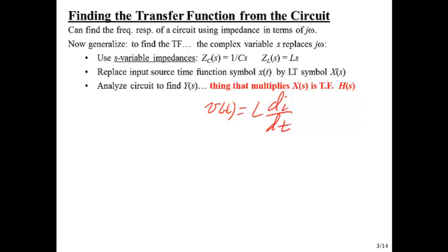Think about taking the Laplace transform of both of those sides and coming up with a Laplace transform version of Ohm's law, and you'll actually discover, if you do that, you'll have essentially discovered why we say the impedance of an inductor is Ls. So that's something for you to try, and we'll talk about that during the class.